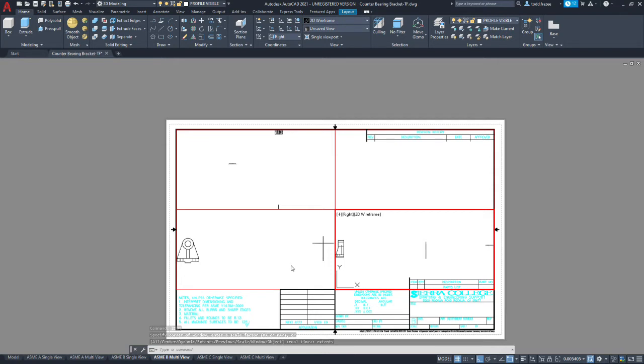Okay, now once you've done that for the 3 of the 4 viewports, we're going to be at step 25, where we're going to center the 2D geometry for each port. And we're doing this somewhat eyeball at this point, and we're going to go through a process that will actually align them to each other. So I'm going to start with the right side view since it's active, and I press down the center wheel of my mouse for pan, and you can use the scroll to zoom in.